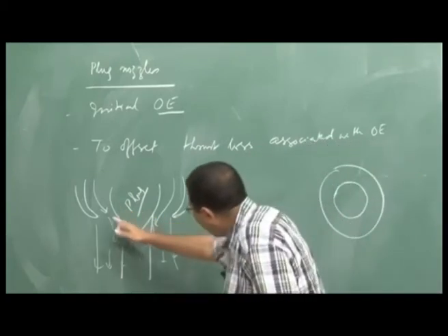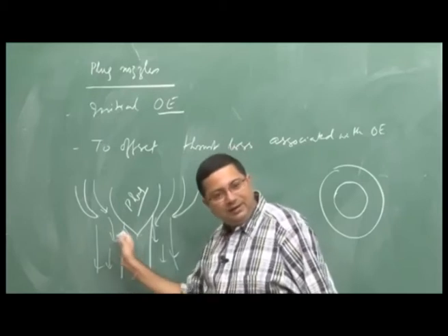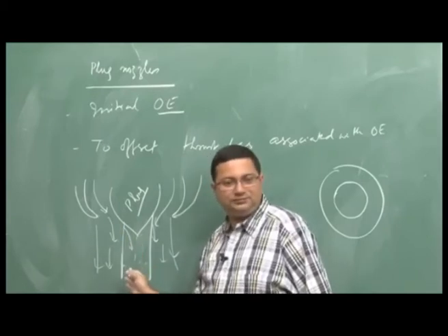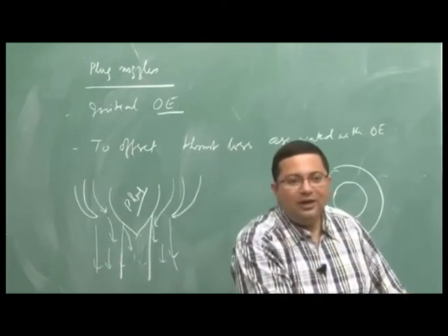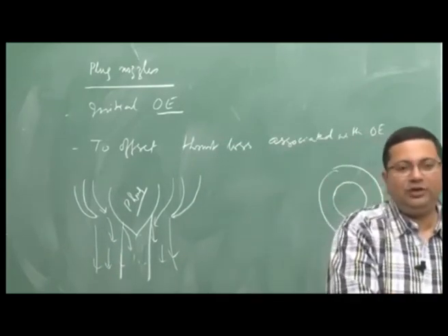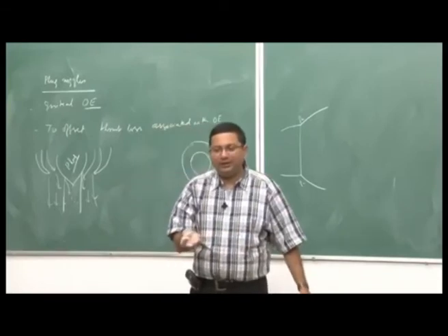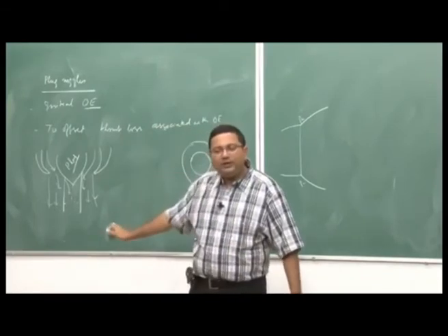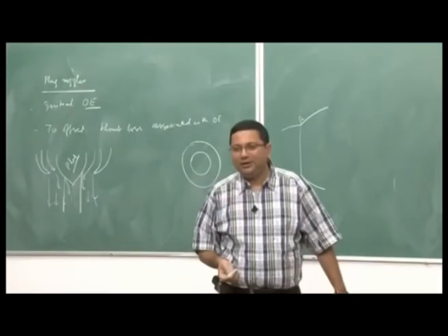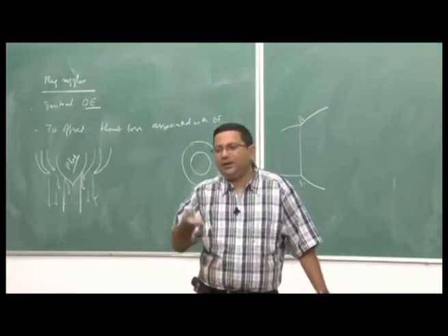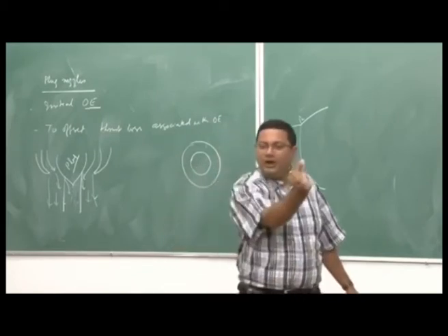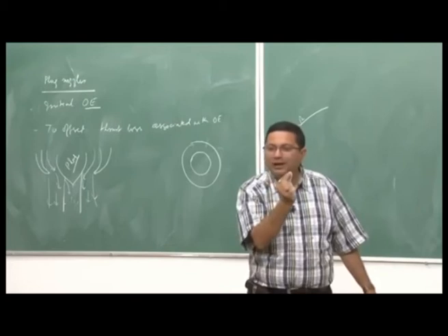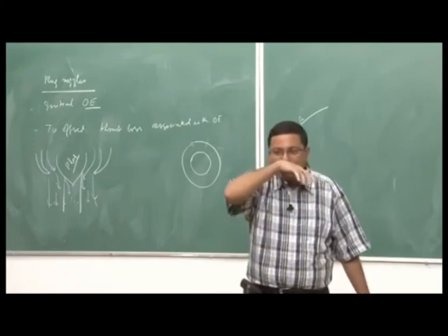this plug can be designed in such a way that there is a gradual expansion. So, therefore, this shock formation and initial shock formation and all can be eliminated. This is typically what is used for supersonic intakes for aircrafts. If you look at a fighter aircraft or a supersonic missile, they have a nose coming out, it is like a plug. That plug essentially serves two purposes.